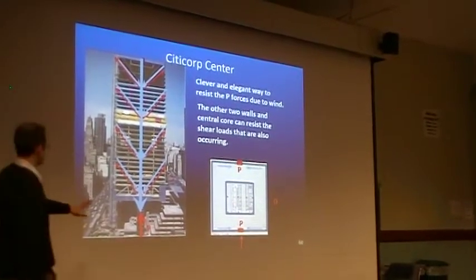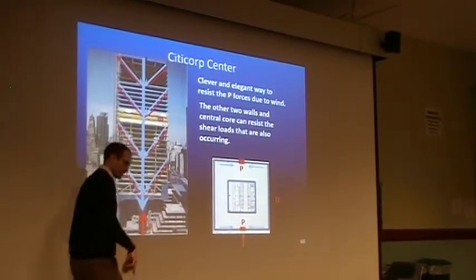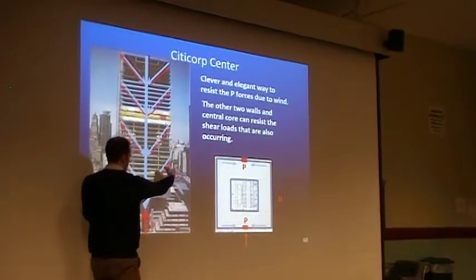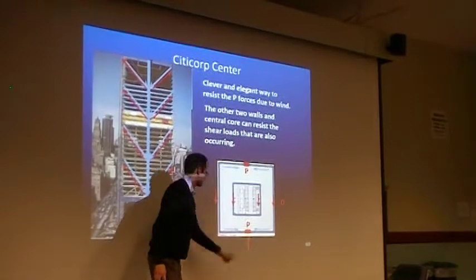Meanwhile, this side's worrying about the tension load, the other side of the building is worrying about the compression load. These side walls are free to worry about whatever shear forces are happening here to resist that. Works out great.